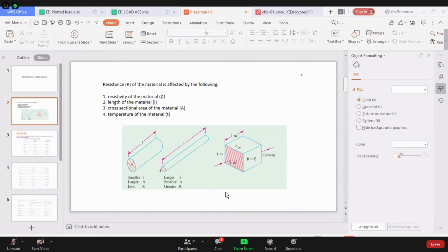No? That explains why our load is supposed to be 220, but if you look at the transformers, the ones on the posts along the road, the marking you will see is 240 volts. So there is a 20 volts extension on the nominal voltage.